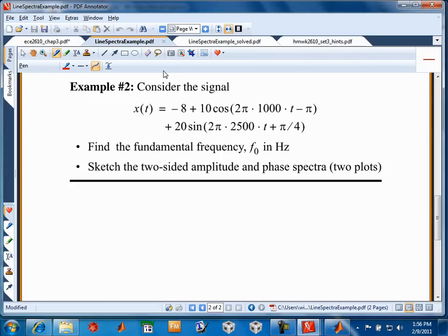And in this particular signal, what's interesting, and this pops up in the last homework problem and things we'll be getting into with Fourier series, the fundamental, just like the exercise in the lab, is not represented in this signal nor in the spectrum. There's no 500 hertz component present. Just like in the previous example number 1, there's no 40 hertz component present. But that determines the period just the same.